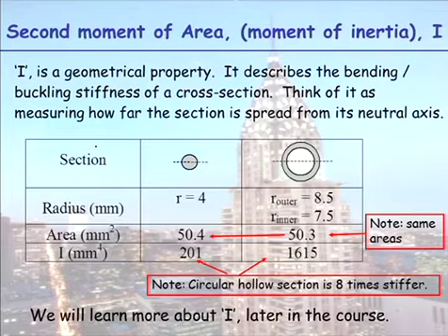So just have one more overhead on what this second moment of area or moment of inertia is. It's a geometric property. My ruler here has a length of 950 millimetres. It is 37 millimetres wide and about 5 millimetres thick. If I say where's the cross-sectional area, you can all see this. This thing has a geometric property called the stiffness, and for a rectangle, that is BD cubed on 12.